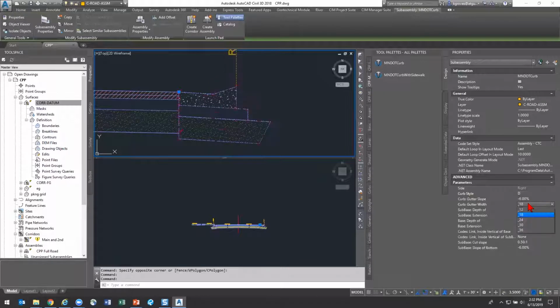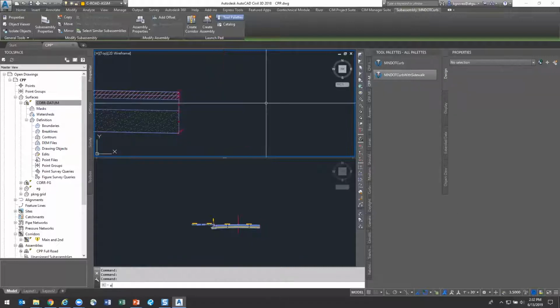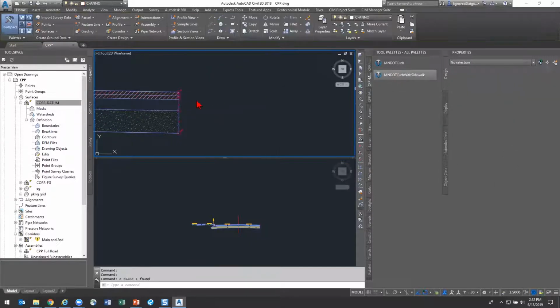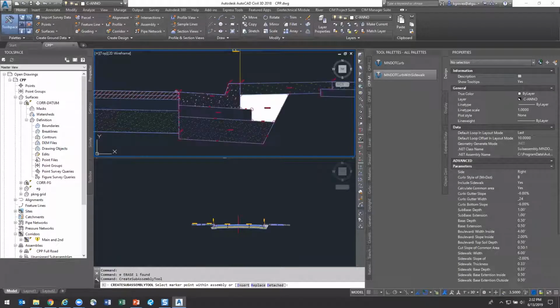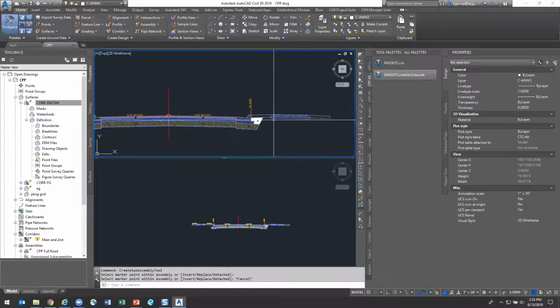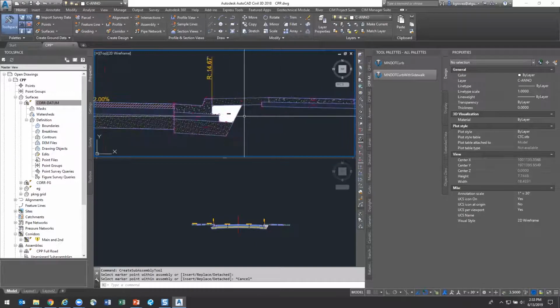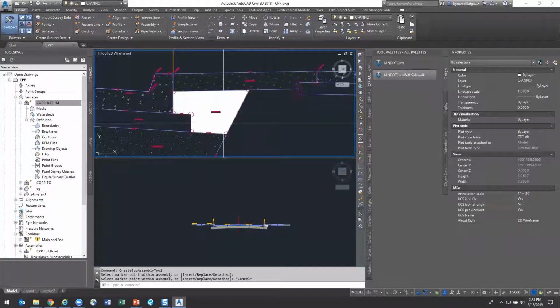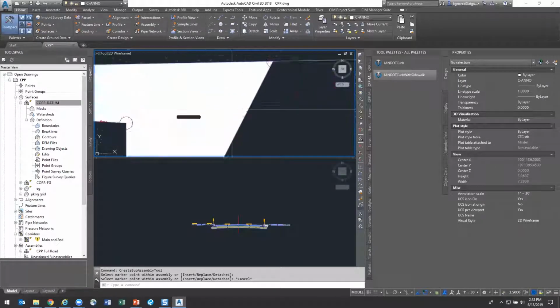We can go ahead and also switch this between a 12-inch flange or an 18-inch flange, and so on and so forth. So those are all per the Minnesota DOT specification. And the other really cool thing is for the version that we had included with the sidewalk, once we put the curb and the sidewalk together, we were able to define a new shape, a shape that you can't get unless you were to create this all as part of one subassembly.